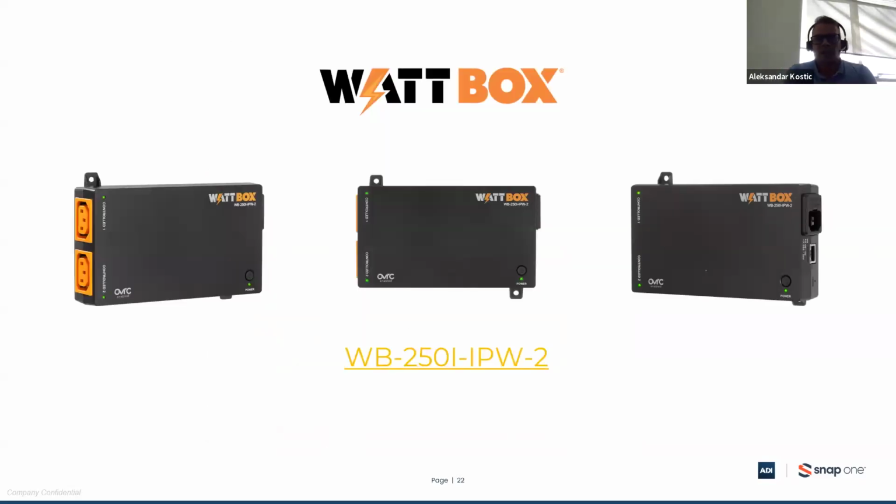So regarding the previous 3 units, what is common for them is the power budget. Regardless of the number of power outlets, whether we have 6, 8, or 12, our maximum current rating for the input and for the output connection is 10 amperes. So if we are using 220 volts on the main electrical network, our total power budget for the 6, 8, or 12 power outlet unit is 2.2 kilowatts. So 2.2 kilowatts is the power budget for any of those 3 models.